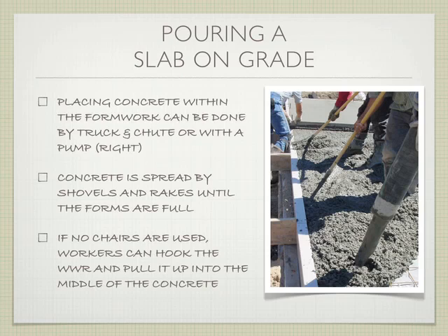Is there a size limit on the coarse aggregate when it's pumped? There probably is. This kind of hose can handle up to 1.5 inches, which is kind of the standard concrete that we get. You're not going to pour a dam that has the big 6-inch aggregates in it with something like this. It's going to be much bigger. So this is for the residential scale that you'd be pumping with something like this.